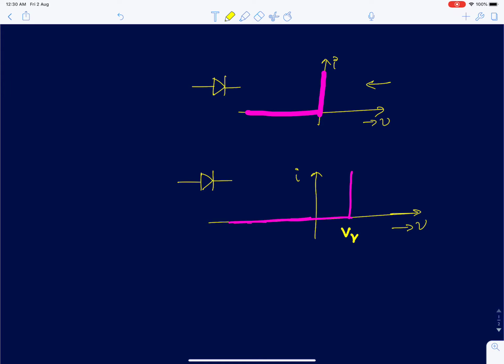Whenever the diode is conducting current, we assume that the forward voltage of the diode is 0, and it behaves like a short circuit. But this is a diode; it can only carry current in one direction. So if I use an ideal diode model, since the diode voltage is always 0 for any value of current, the power dissipated across the diode is 0. The DC power dissipated across the diode is 0.